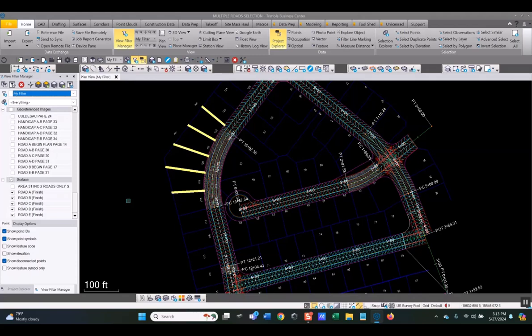So that's the base way, I guess you might call it. Some people do, some people don't. But anyway, selecting individual pieces, parts, entities, you pick one entity first, then you press and hold down the control key, and you can start individually picking whatever lines, pieces of text, any particular objects. It doesn't make any difference.